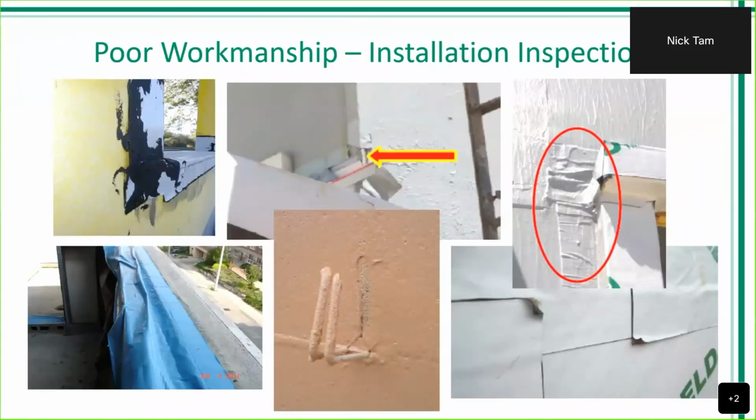Also, we want to make sure that we have a smooth and clean application of these materials. The top is a good example of someone trying to treat the edges of the flashing, but because it's not very clean, it may be easy to miss areas that we didn't treat appropriately. And if they have wrinkles in these membranes, that just creates a new access point for moisture to creep in, especially at the fish mouths. And over time, it can just come disadhered anyways. Also, at the very bottom, when we mentioned spraying over those brick ties, do note that we want to get behind them as well. If we miss them, then we have jeopardization in the continuity of the membrane.